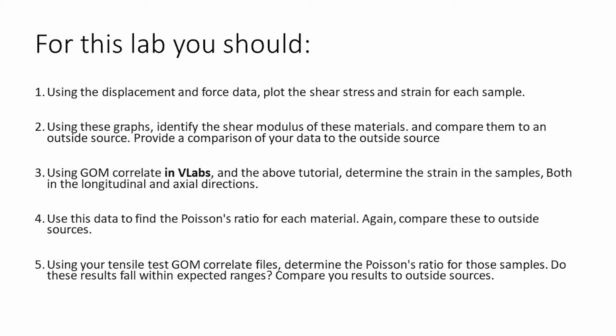Finally, using the tensile test data from our first lab, you'll perform the same experiment in GOM Correlate to identify the Poisson's ratio for each material. Do the results for these fall into your expectations? Let us know again why or why not.